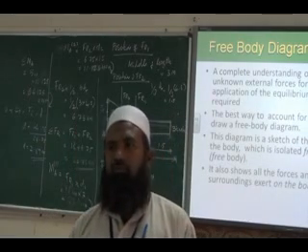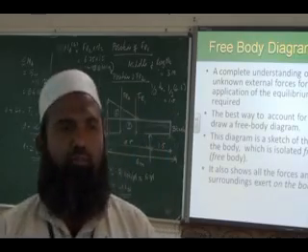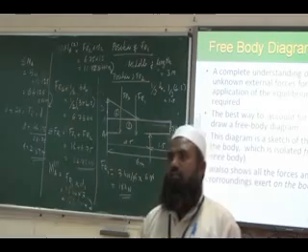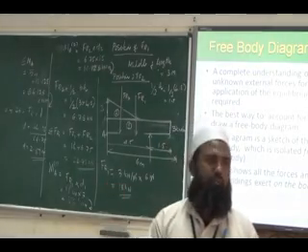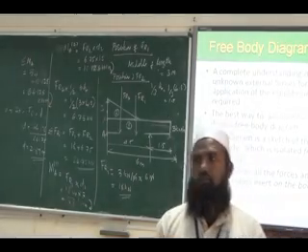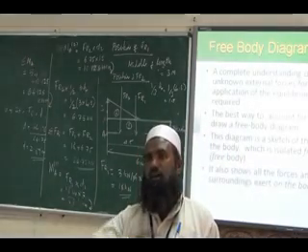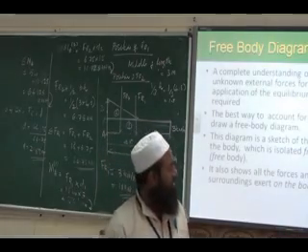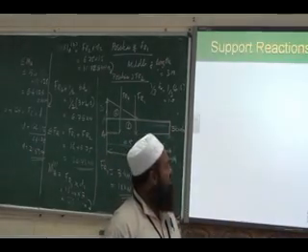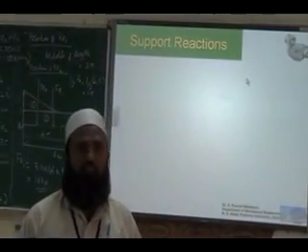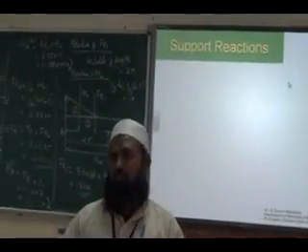Okay. So we have to consider known forces as well as unknown forces. Forces applied are known forces. Forces which are developed due to the applied force, an action which produces a reaction, those will be the unknown forces. That will account for all the forces. Okay. So in order to consider the unknown forces, we must know about the support reactions, the reactions produced by the supports.